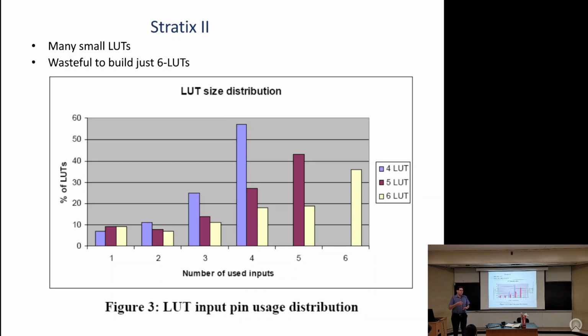Or more commonly, when you get things like arithmetic, you might just not be able to use the LUT. It's just acting as a feed through to get to a structure that can do arithmetic. So there are reasons why this happens, although it still looks a little surprising. And I'm giving you plausible reasons, because otherwise you kind of go, the synthesis team needed to work harder. But anyway, we're not using the 4 LUT to its full capabilities.